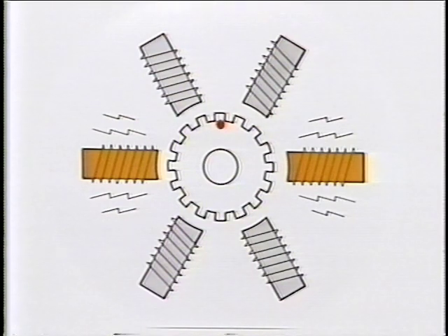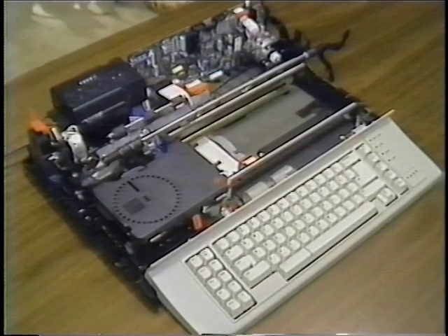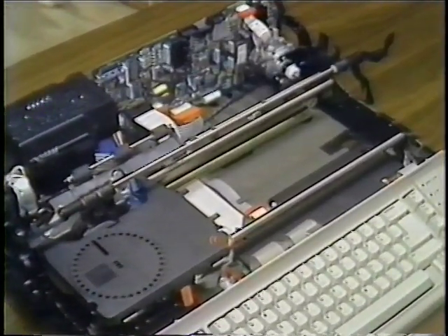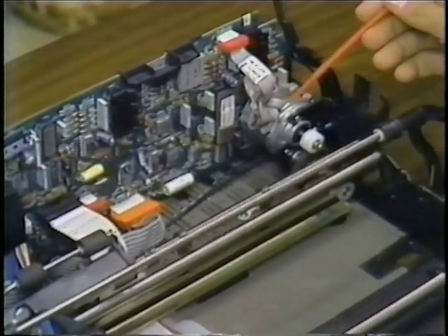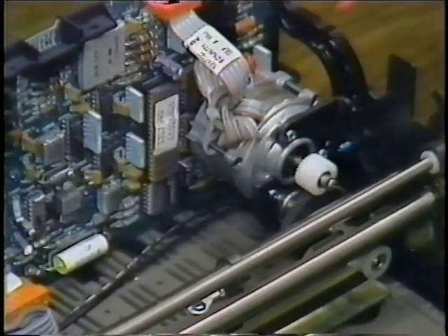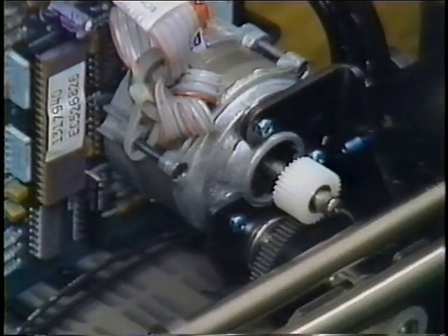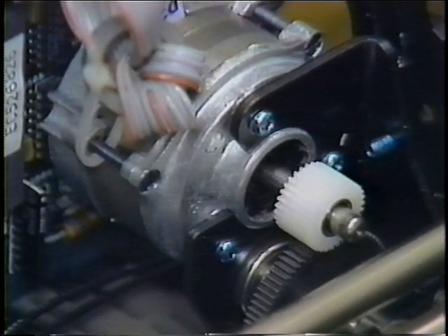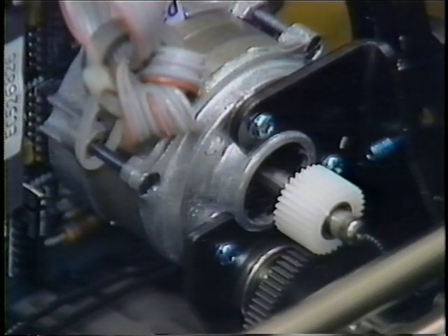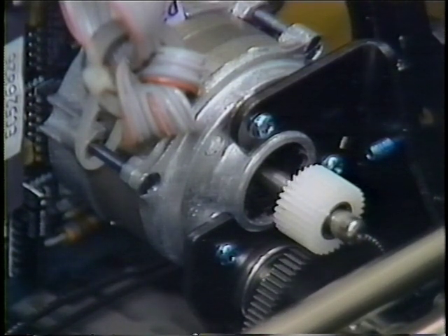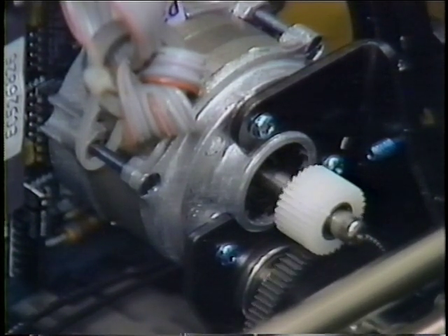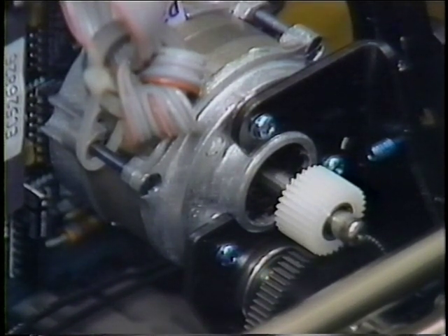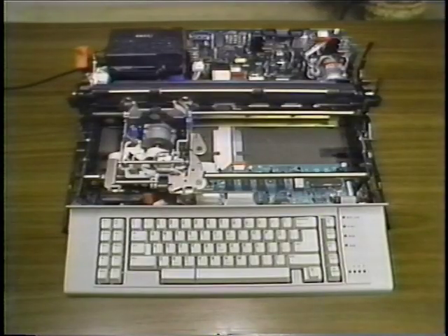3 of the stepper motors in the Wheelwriter 5 have detent modes. They are the selection motor, the transport motor, and the ribbon lift motor. Because of the electronic control, stepper motors are able to perform operations not possible with other types of motors. For example, a stepper motor can start, stop, and reverse direction extremely fast. The most important feature of the stepper motor is precise control of the amount of rotation. This completes the technical overview.